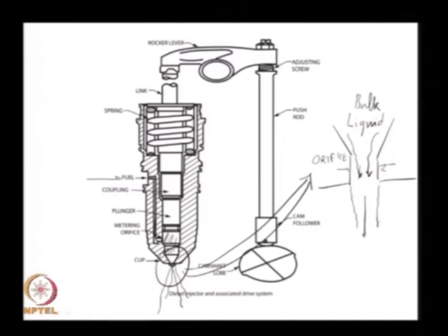This jet is moving at some velocity. So, I have taken the spring energy, converted it first into pressure energy in the liquid, and that pressurized liquid is accelerated through this converging passage to give me a fast moving source of liquid.